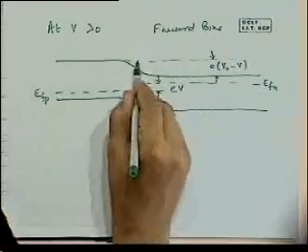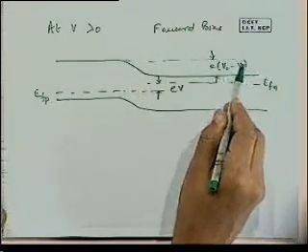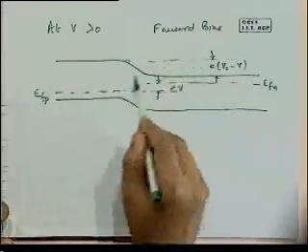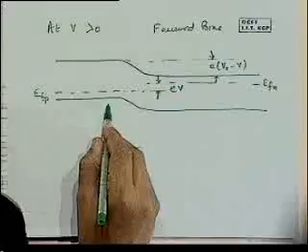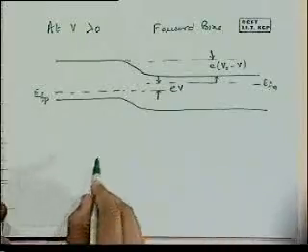So here, because of this lowering of the barrier by e(V0 minus V), what I discussed, I'm just putting it together again graphically, we have now that electrons can flow over this lower barrier as a consequence. And the same would be true for holes, they can flow in the opposite direction.